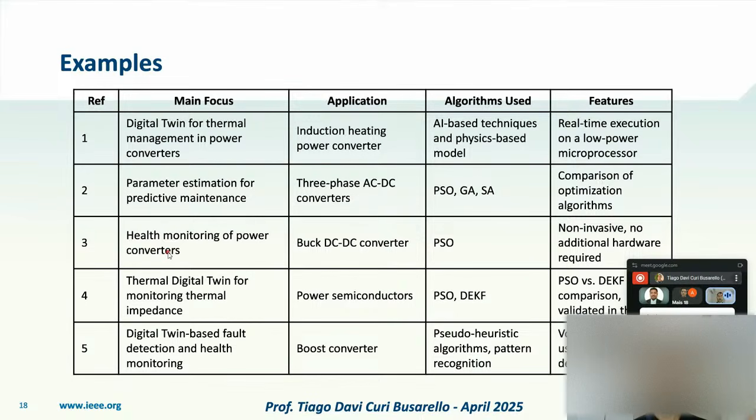We know that when you buy everything new, you build a buck converter with new components, then you put your converter to run at the nominal power, at the rated power. You measure the case temperature, you measure everything you can. So as new, you have such a temperature at the rated power.